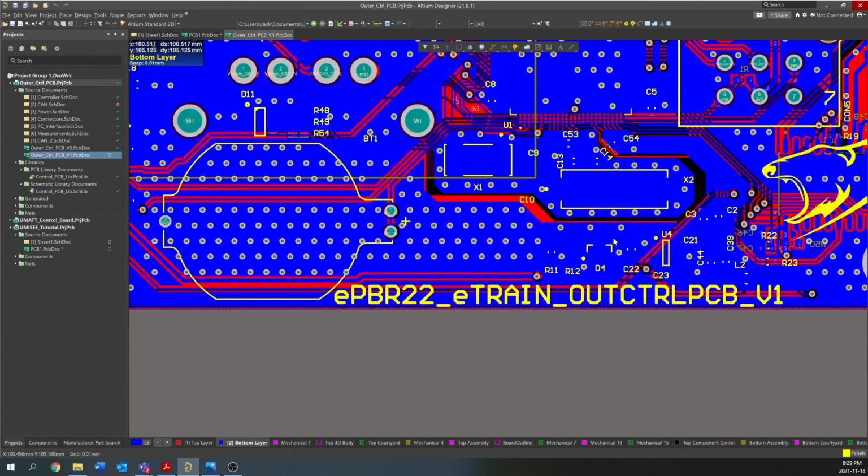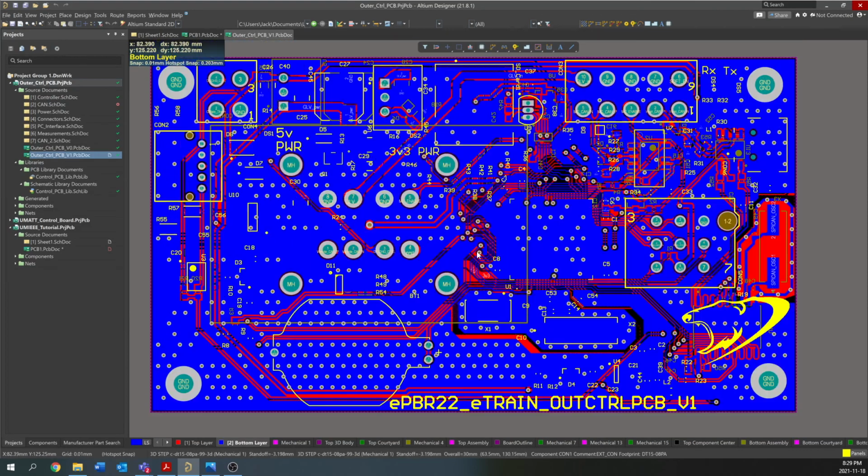Altium does that automatically, and that essentially nets the two pours together, so it's kind of equipotential, and all those different areas of the pours that are split from each other get connected, because most likely at least part of that polygon on the other side connects to the ground polygon that's close to it, and then it ends up connecting the whole board.